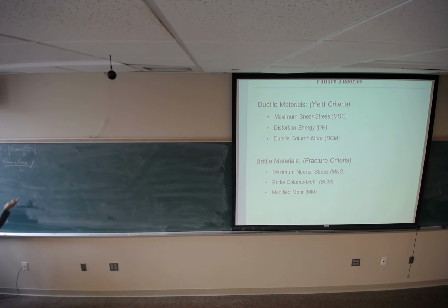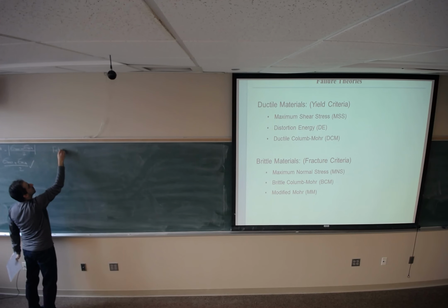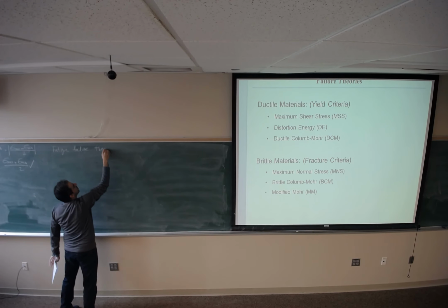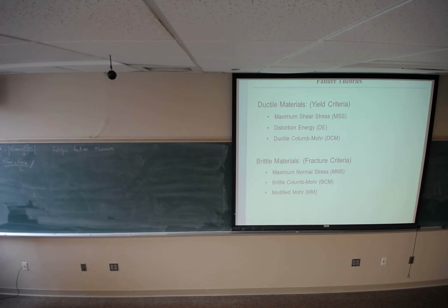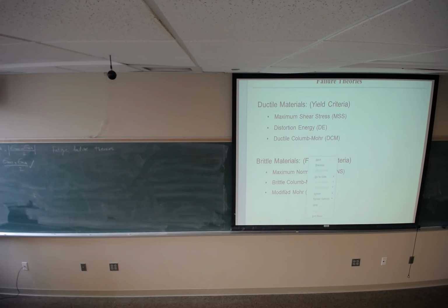But for a fatigue problem, when we have fluctuating stress, meaning we have sigma m showing up in the problem, we need to introduce some failure theories. So I'm going to introduce some fatigue failure theories. These theories are going to help us to predict the failure. Similar to what we did on static failure, I'm going to do this for fatigue problems with fluctuating stress. For non-fluctuating or completely reverse cycles, we know how to do that.